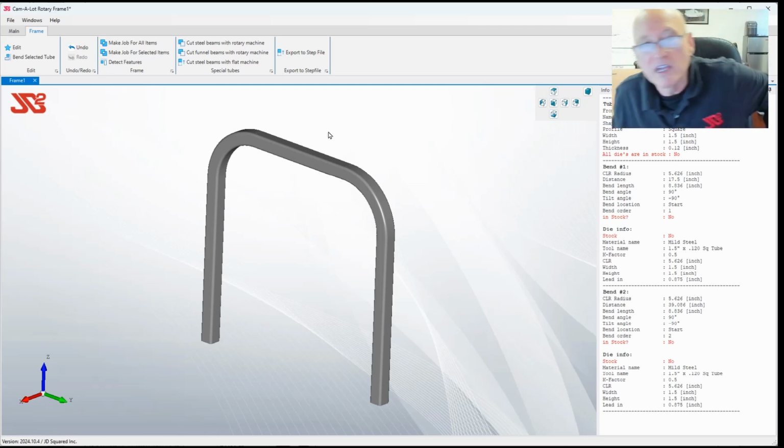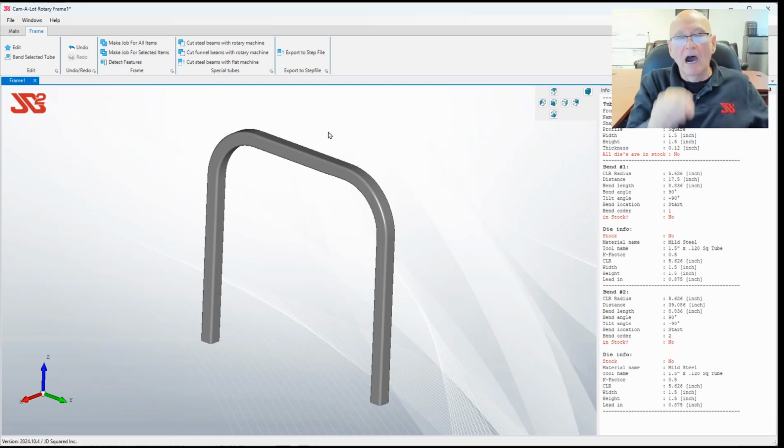So across the two different machines, if we automatically changed your K factor to what you just measured, then here comes the next guy. He wants to use the program to generate a bend for the other bender. It is now wrong because you changed his K factor. So typically when you do K factors, they are specific to a machine.